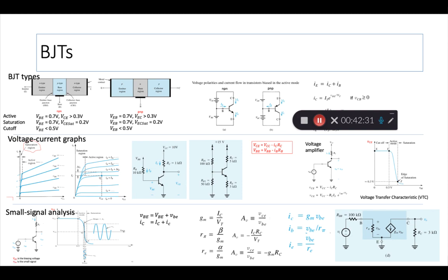And for linear operation, you have a simple superposition that gives you the output total voltage and total current, right? Total voltage and total current, meaning the output. V base to emitter, this is the input, right? On the input side, you can say V base to emitter is V_BE, capital, big one, that means the DC, plus the signal v_be, right? That's on the input side.